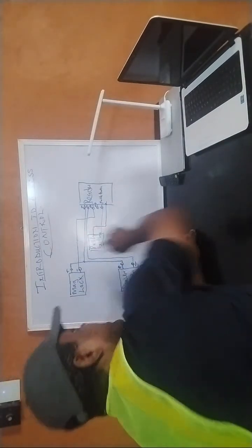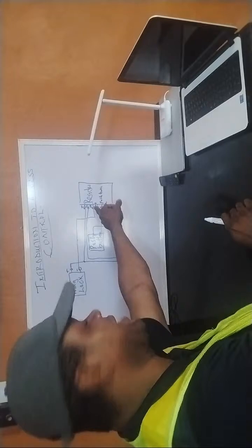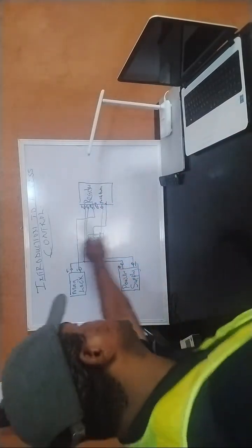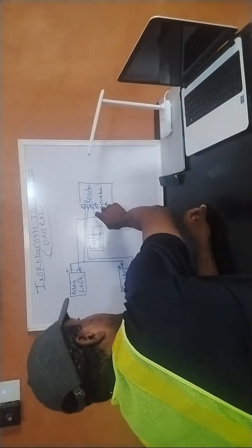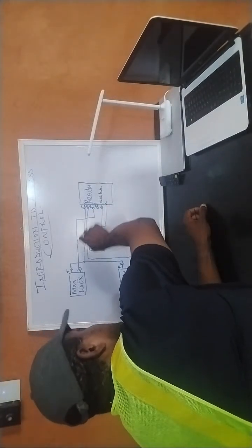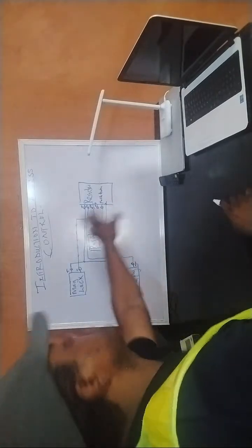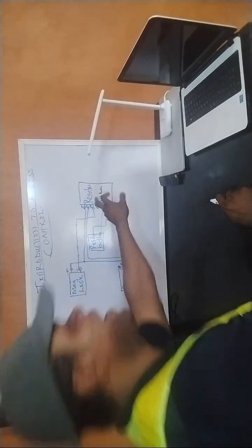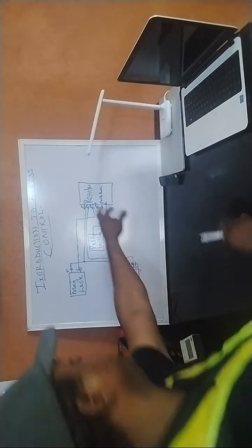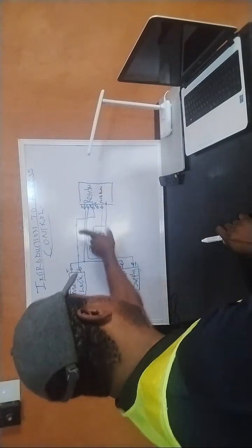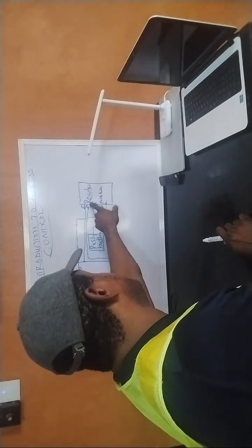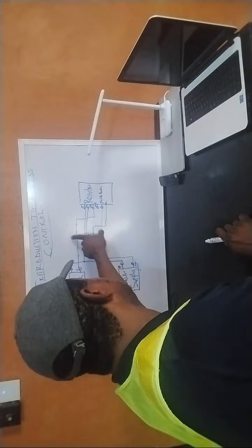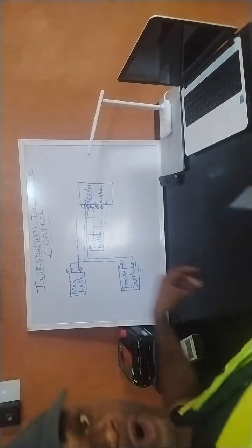Let me close it back. A normally closed contact's rest state is closed, so there is current flowing through this because it's closed. But maybe you send a signal to this reader, and there's a trigger in the relay of this reader, then the normally closed from here will open up and become closed with the normally open. Then the supply here is cut off.